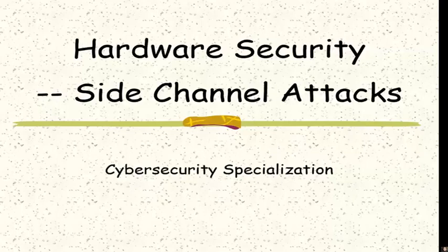Side channel attacks are perhaps the most successful attacks on modern cryptographic systems for two main reasons. First, they target the weakness of the implementation of the crypto algorithms, not the algorithms themselves. Therefore, a mathematically sound algorithm can become vulnerable to side channel attacks. Second, these attacks are non-invasive, passive, and most of the time will not leave any trace of attack.